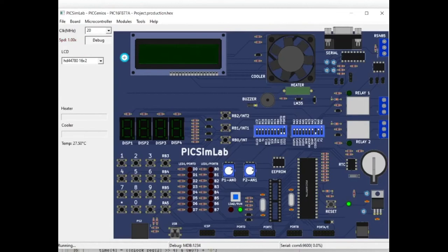Now I do reset. Now I enter the correct password, and you can see the login screen here. By selecting view log using RB5, you can see the logs here. By RB4, we can navigate through view log. As I press the reset switch, currently no events are there.